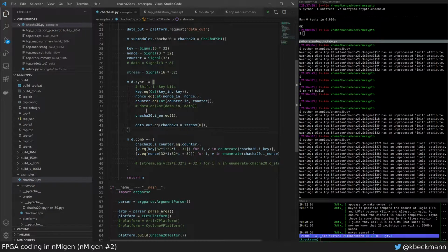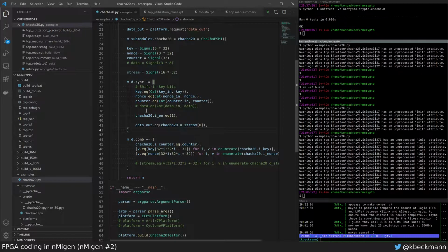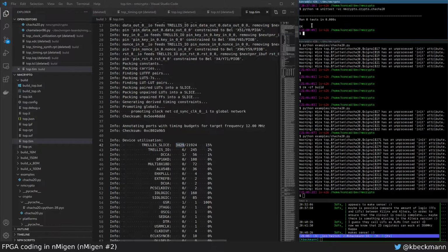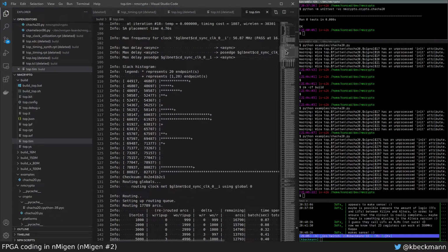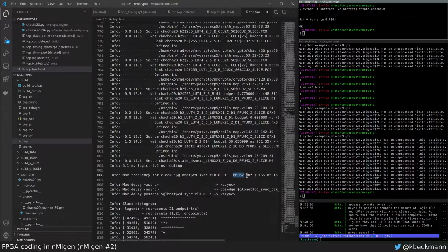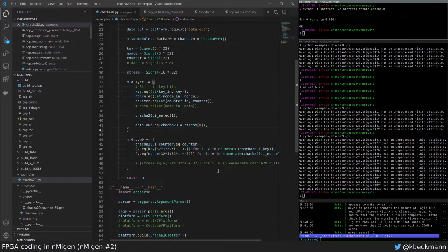It's always kind of hard doing synthetic profiling things when you don't have a reasonable logic core. Oh shit, look at this. It's using tons of logic. Like this is using like 1000 extra slices just because I'm using that shift register stuff. But the timing at least seems to be okay. Yeah. I don't know really what is a good way to...